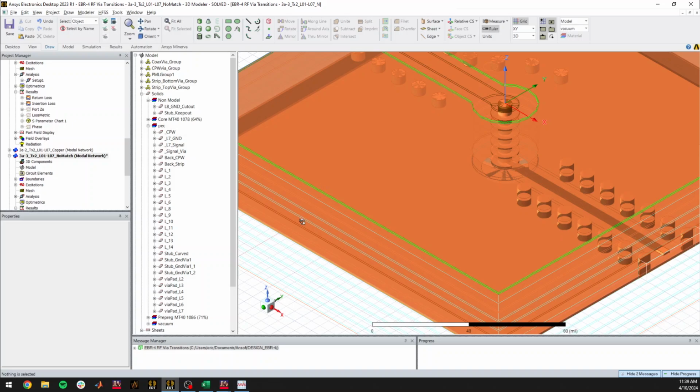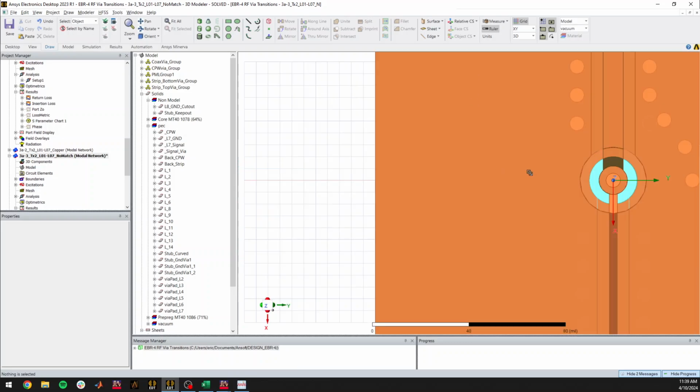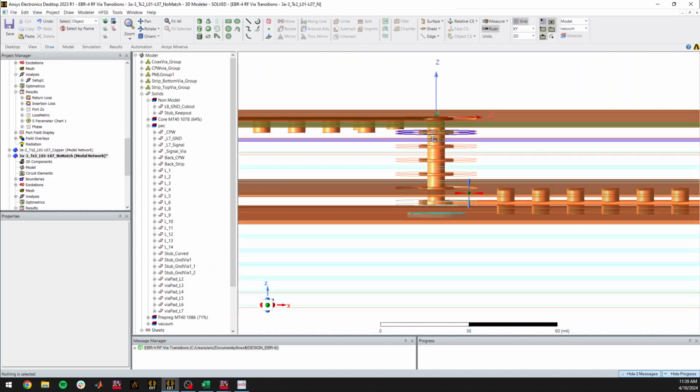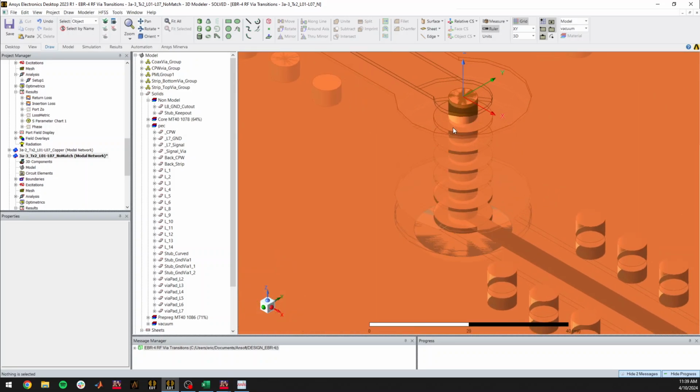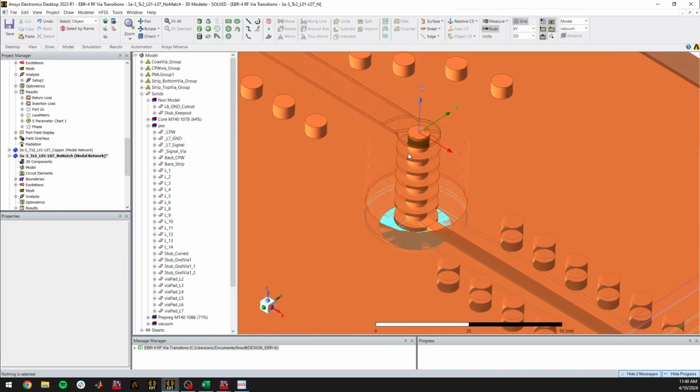So, in this transition, we're looking to go from essentially 50 ohms to 50 ohms, or needing to do that, in a manner that doesn't eat too much of our signal or impact our performance. So, inherently, you're wanting to design some sort of transition that looks like 50 ohms. And in this case, you have your signal right here, and in addition to your signal, you do have via pads on each of your layers in between the top and bottom layer.